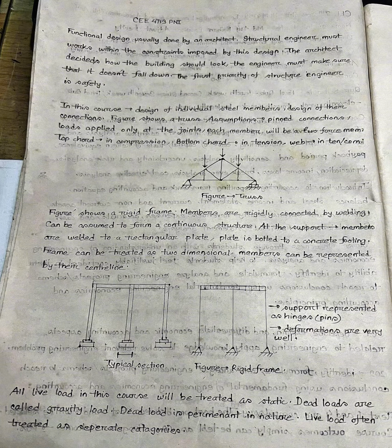The frame can be treated as two-dimensional. Members can be represented by their centerline. Supports are represented as hinges. Deformations are very small.